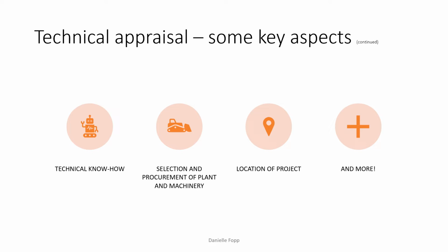Now, the machinery and equipment required for a project depends, obviously, upon the production technology proposed and also the size of the project. We also then need to look at the capacity of each machinery and decide what's actually going to be suitable. So, for example, in construction operations, we look at the sizing of cranes. So that would be one such item that you would be looking at. Do we actually have the capacity of machinery to complete the project?